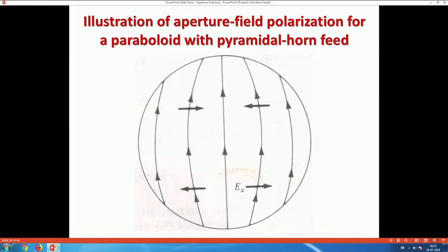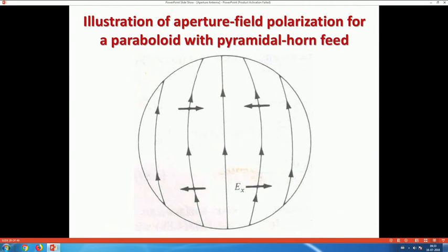Actually, I have a large surface, and there we are assuming that we have, suppose, a polarization like this, but because this is an aperture surface, there is no point in preventing the cross polarized field. So, some cross polarized field will come because the horn is also giving that cross polarized component, then there are scatterings, and various reflections on the feed, etc. All that gives this cross polarized component. That also needs to be taken into account and can be estimated, but we are not going there.